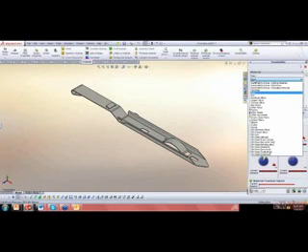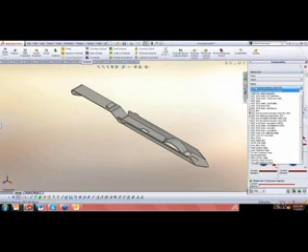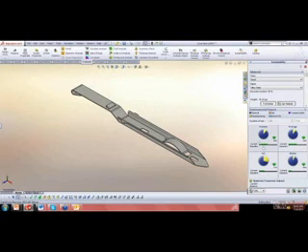The class will go for steel. The name will just go for, for example, alloy steel, right? And over here, I will click set to baseline. Okay, so meaning that I set currently design one is this value.